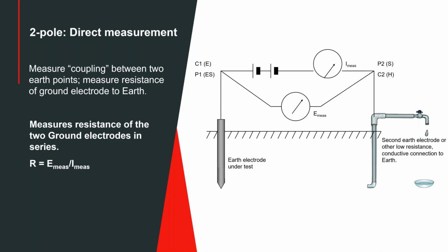The water pipe or fence is not part of an electrical system. So in that respect, it's dead. And so you see the term dead earth in the literature. And so this is a 2-point measurement where your test current is now going from your electrode that you're measuring through the earth out to some arbitrarily selected point of return, such as the water pipe system.